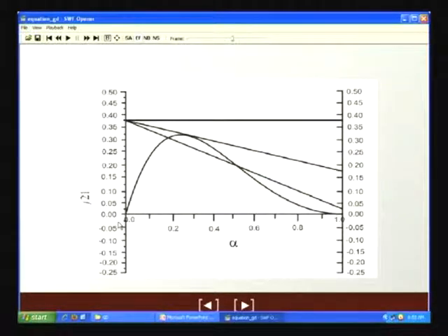So, for counter current flow with gas up, liquid down, we all know that it operates within a particular stable operating range, and that range is limited by the flooding condition at one end, the weeping condition at the other. Okay. So, below the flooding point, we find that we can get counter current operations under two conditions.